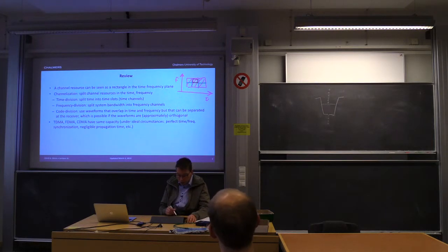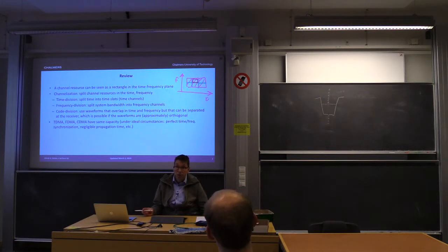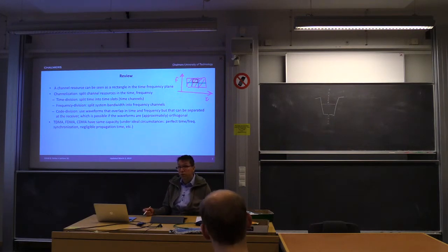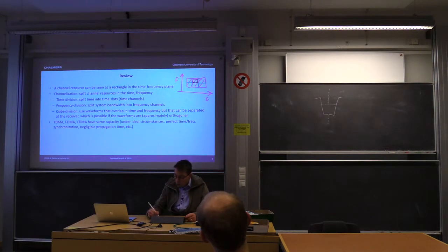So then a natural question, there's been a lot of debate about this, which one of these is the most efficient one, which one should we select? And the simple answer to that is that on a theoretical level, they are all equivalent, so there is not one which is better than the other. On a practical level, it depends, because in the isolation that we did here in time and frequency, typically one has to put in some guard intervals, maybe in time, like this, where we cannot use the channel for a short period of time, and this has to do with the propagation delays and so forth over the channel.